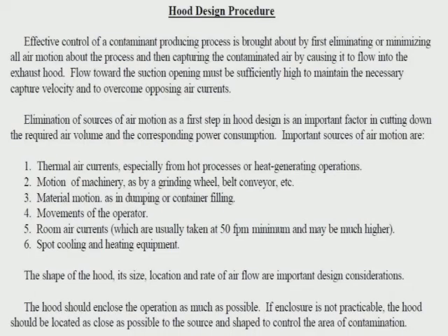All right, some hood design information. These apply not only to slotted hoods, but to canopy hoods as well. I guess the most important information on this page is that elimination of sources of air motion, as a first step in hood design, is an important factor in cutting down the required air volume. So you get an idea there. This talks about thermal air currents, material motion, even movement of the operator.